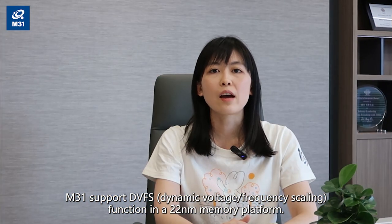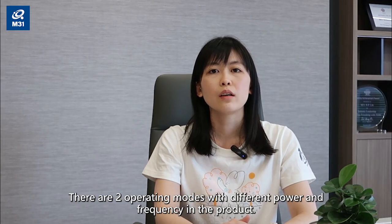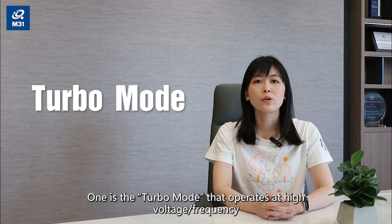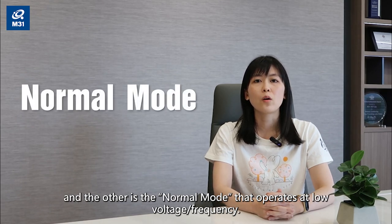M31 supports DVFS, dynamic voltage frequency scaling, function in the 22nm memory platform. There are 2 operating modes with different power and frequency in the product. One is the turbo mode that operates at the high voltage frequency, and the other is the normal mode that operates at low voltage frequency.